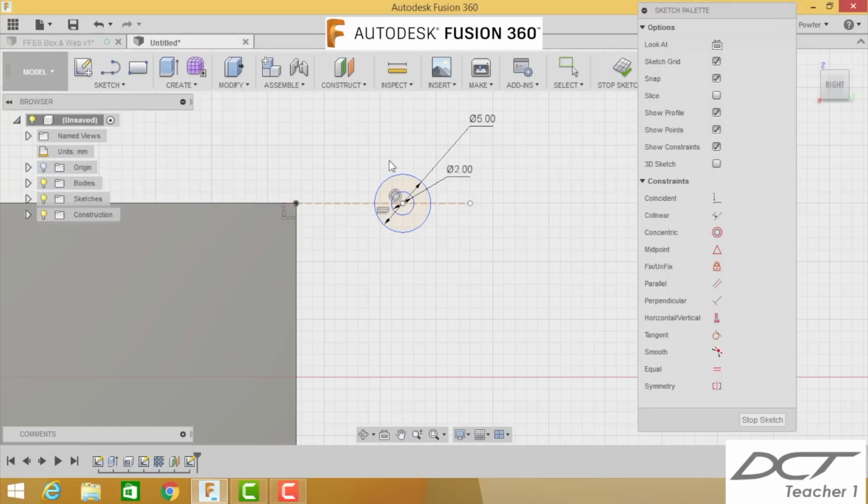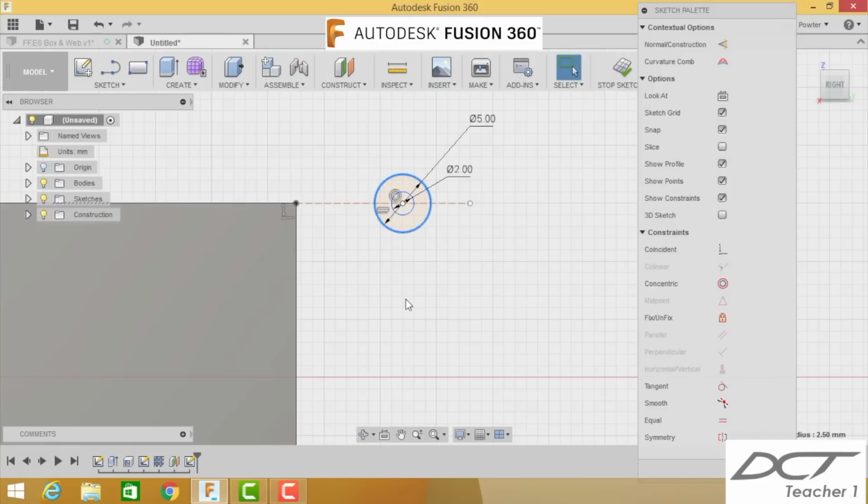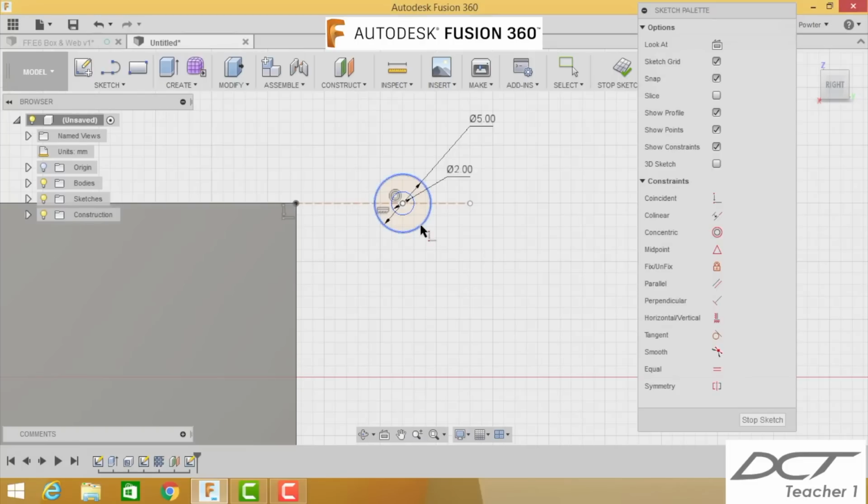We're not encyclopedias. Okay. What I want to do now is click this outside diameter, hold my shift key down, and escape out of that because I still had dimension up. Click the outside diameter here of the circle, hold the shift key and pick that edge. What we're going to do now is make this coincident. Okay, this button here, and it should snap over. That point, sorry, my mistake.